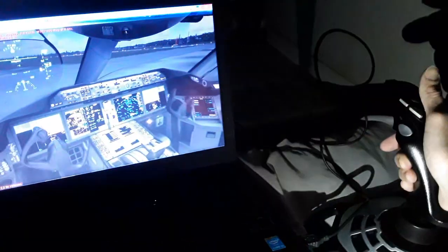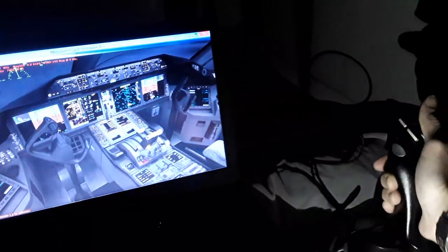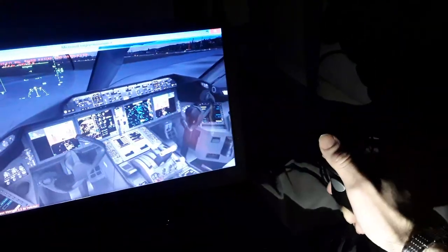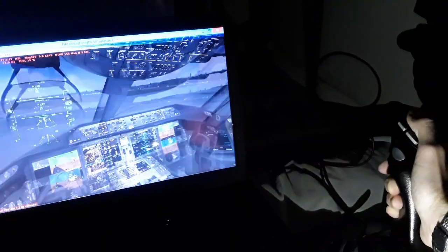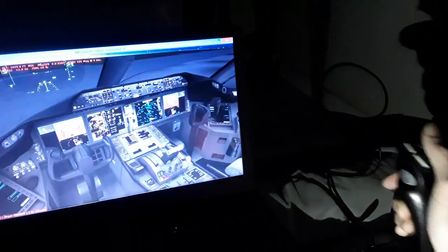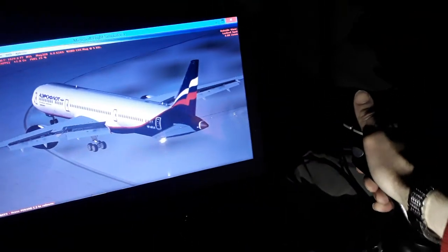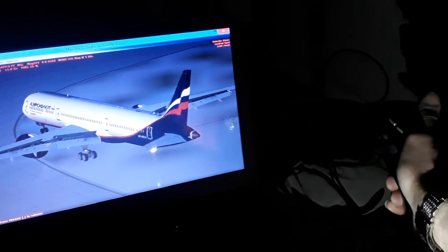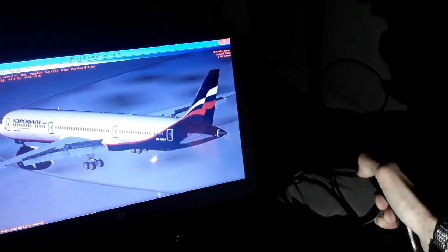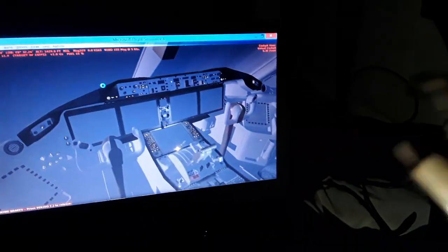So we have the electric control movement because we have a fly-by-wire. When we move the flight controls, the yoke around, they're electrically controlled but hydraulically actuated. So you see the elevator here, the tail needs hydraulics power and pressurizer from the engines to pressurize the hydraulic fluid, and compressors, the hydraulic pumps, the engine driving and the electric driving.